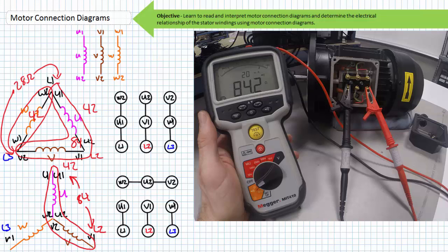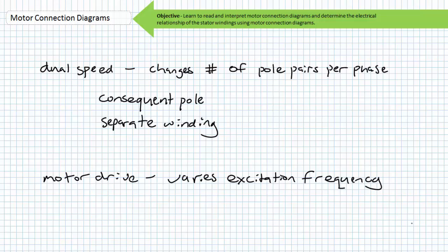This is a great sanity check. 42 plus 42 is 84. Because this is a balanced three-phase AC load, 2-point resistance measurements at all three corners would yield the same result. We can rest assured this motor is wired in a Y configuration. That's about it for dual voltage motor connection diagrams.